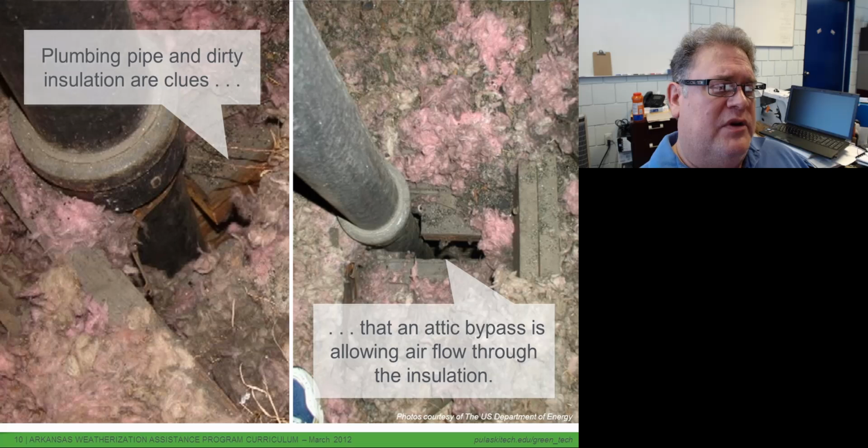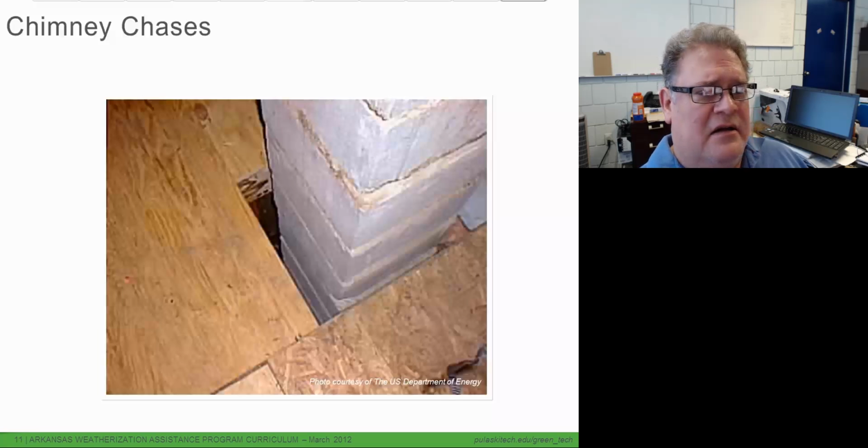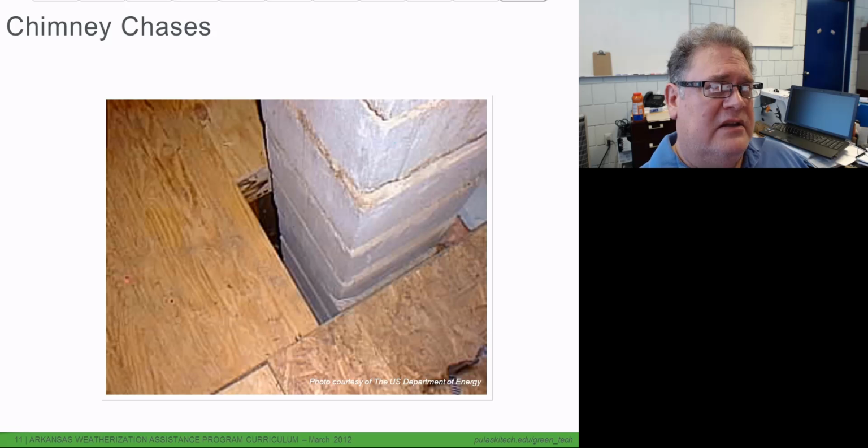Now here, what we would do is come in and we would seal that hole, air seal it. But look for dirty insulation. That's usually a telltale sign of air moving through insulation. The insulation is filtering out the dirt.